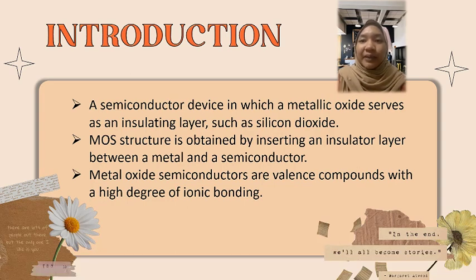Their conduction band minimum and valence band maximum mainly consist of the metal ns and oxygen 2p orbitals, respectively. In general, the metal ns orbitals are highly dispersive while the oxygen 2p one is localized, which results in smaller effective mass for electrons compared to holes. In order to achieve p-type conductivity in metal oxides, the hole effective mass should be significantly smaller.